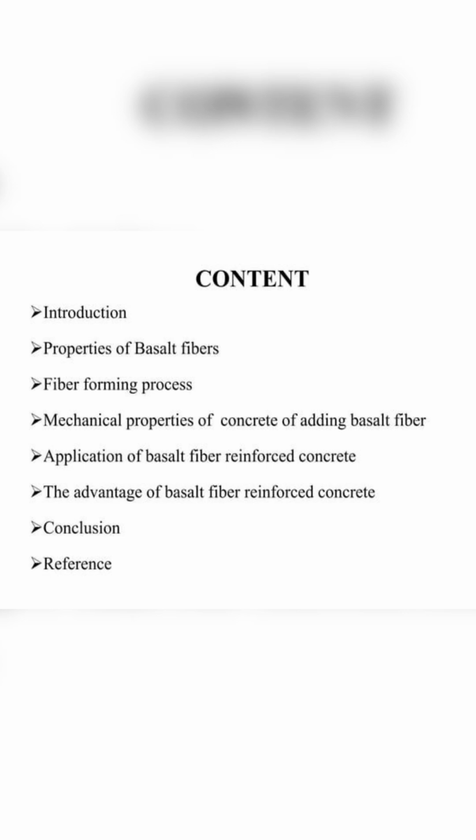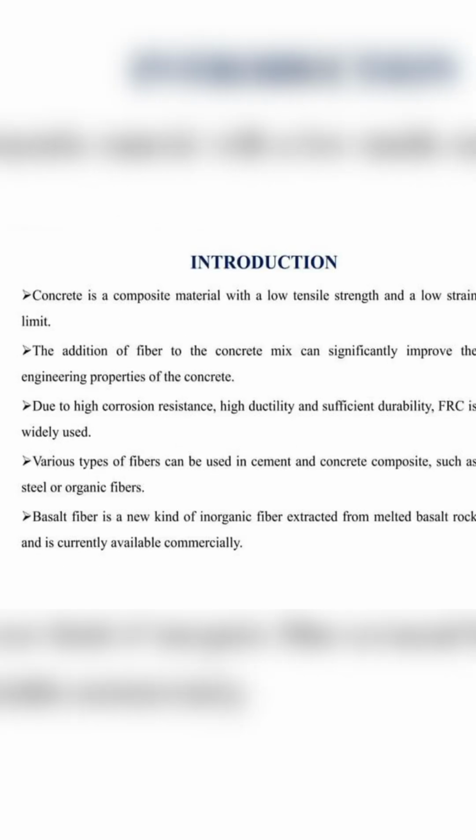This is the content of this presentation. Concrete is a composite material with a low tensile strength and a low strain limit. The addition of fiber to the concrete mix can significantly improve the engineering properties of the concrete. Due to the high corrosion resistance, high ductility, and sufficient durability, FRC is widely used.